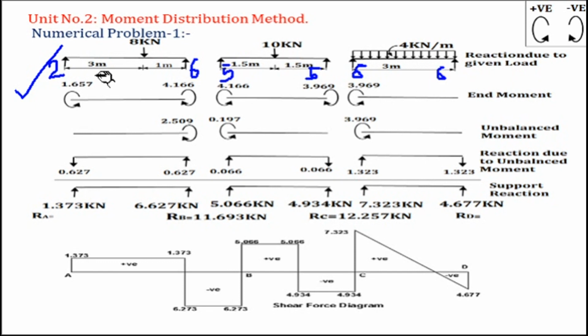Okay, so these are the reactions from the loading. By just doing summation Fx, summation F, and moment about any joint, you will get the reaction, vertical reaction or shear force due to the loading. Now next one, draw the end moments.